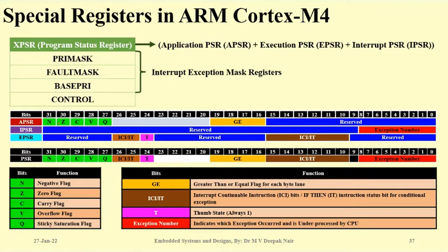Clear? Otherwise, actually they are 3 different registers, but they have been managed in such a way that none of these 3 registers' bits conflict with each other's job. So in total you can combine them together, and you can call them PSR. There is no such separate PSR register. It is a combination of these 3 registers.